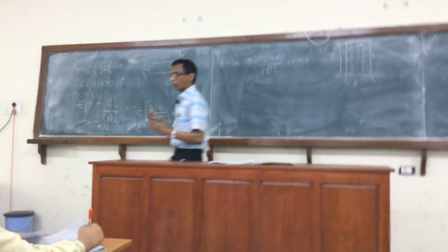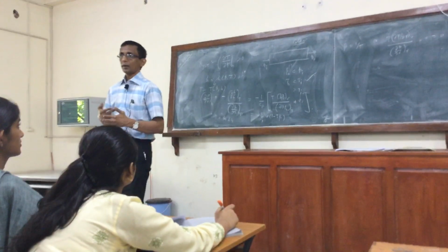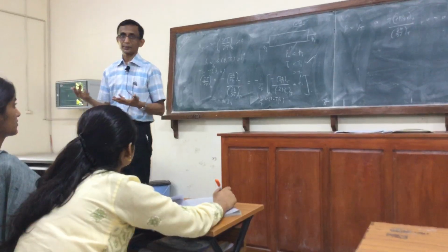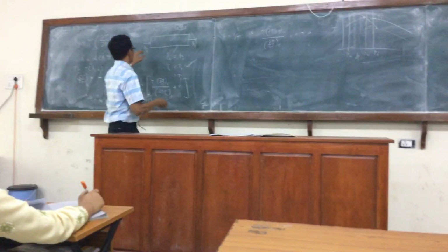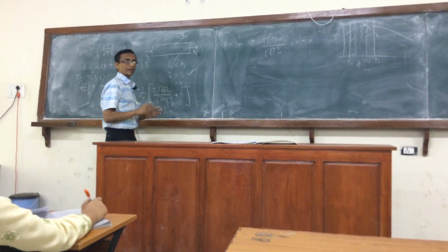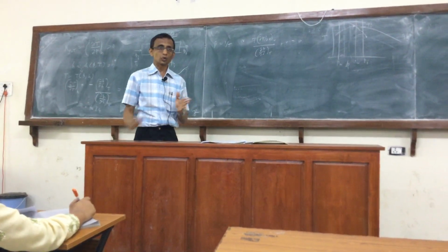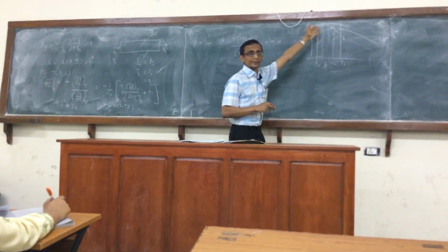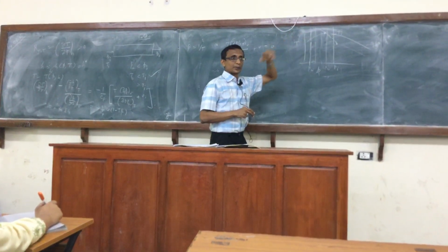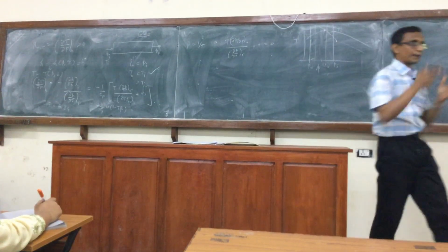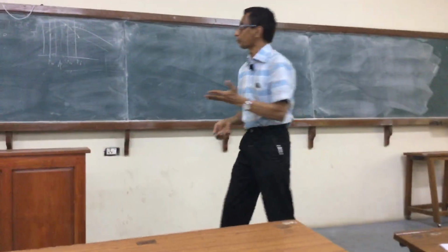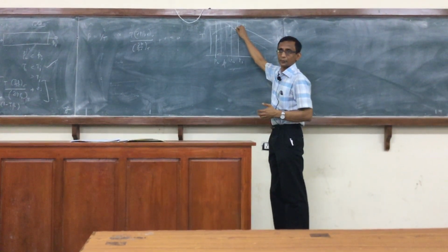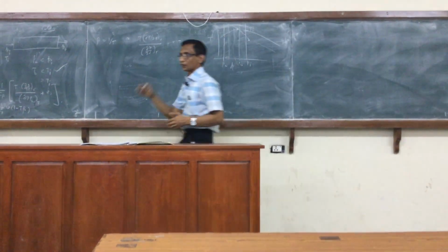So depending on what Pi and P naught are, you will get different temperatures at the exit. That's what it means. Once I have fixed Pi and Ti, I also fix the enthalpy, which is going to be fixed for the entire process. So I focus on that curve, that value of the enthalpy that I have plotted. Now I have to place Pi and P naught. Once I place Pi, it is automatically determined on this curve, corresponding to the actual enthalpy of the fluid.